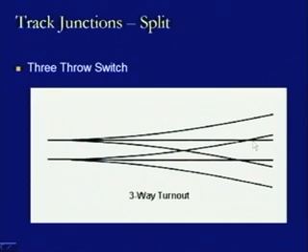Then we come to this particular location, and again there will be a crossing at this location as well as this location. That is why we will be having one wing rail condition at this location also. So, that means we are having 3 crossings and 1 point and switch, but with the 2 sets of tongue rails.